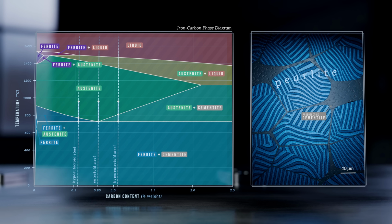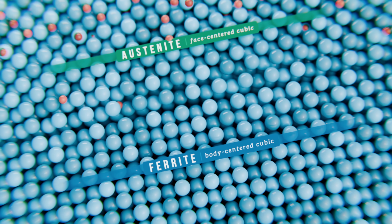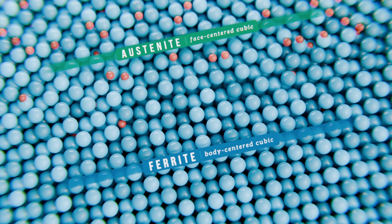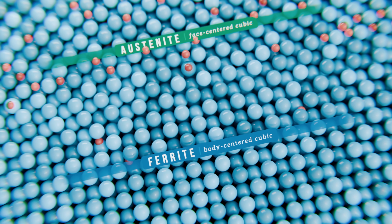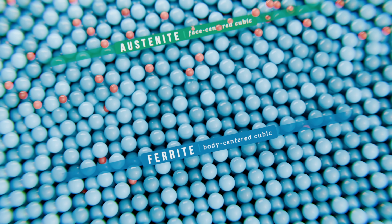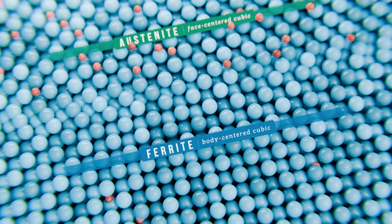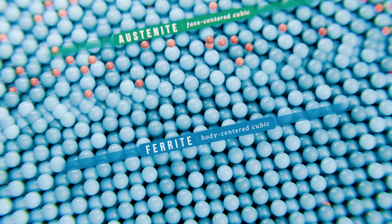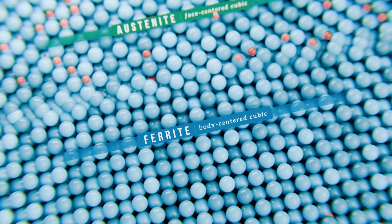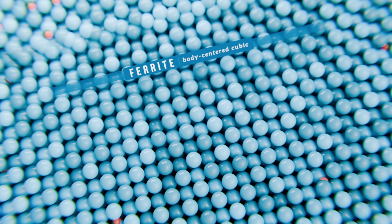All of these transformations rely on diffusion, the movement of carbon and iron atoms through the lattice to form new phases. Because diffusion takes time, the iron-carbon phase diagram only represents equilibrium conditions. It assumes cooling and heating occur slowly enough for the atoms to fully rearrange into the most stable phases. But it can take minutes, hours, or even days for austenite to fully transform into ferrite, depending on composition and temperature.